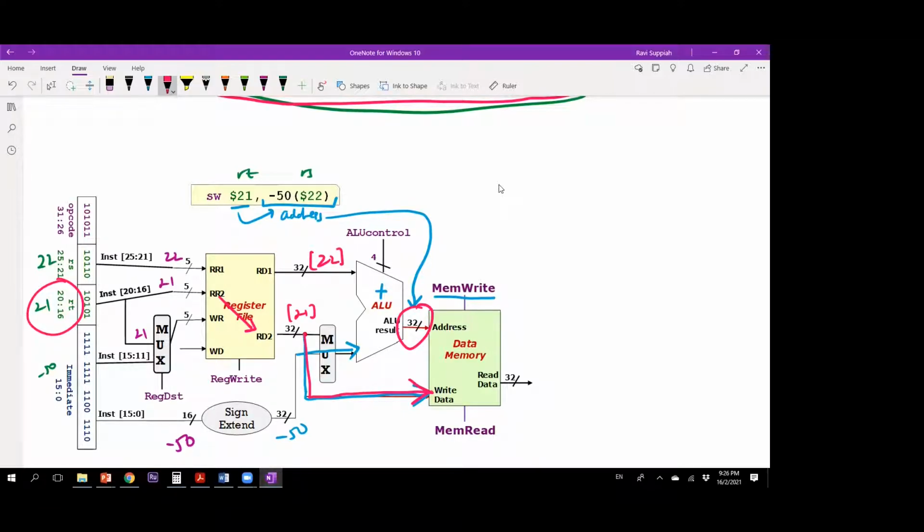So this is again hardwired. We are not explicitly doing it. There's no way to leave it blank, the WR? No, it won't be blank. There'll be something there, but it makes no difference because we will not activate the register write, right? That's right, because for store word, the storing of the word will be done in the data memory area, right?